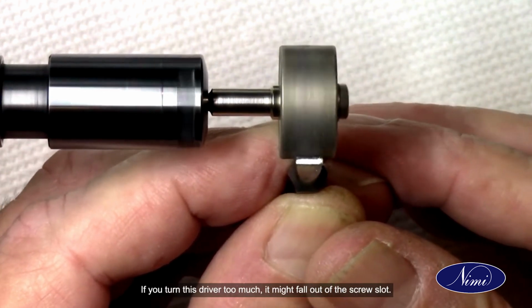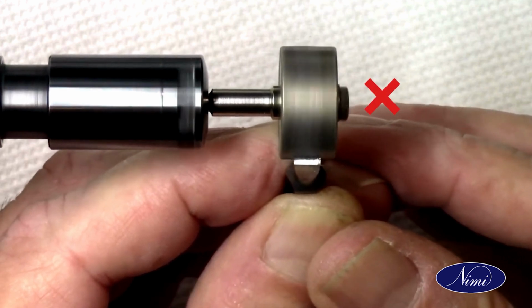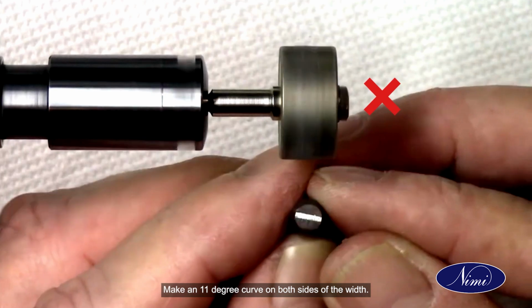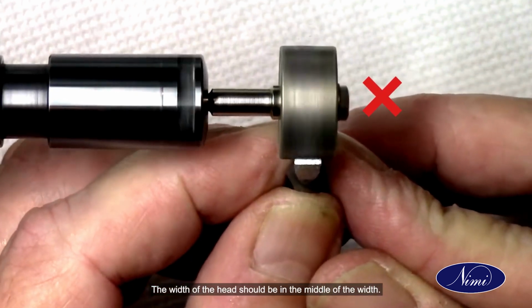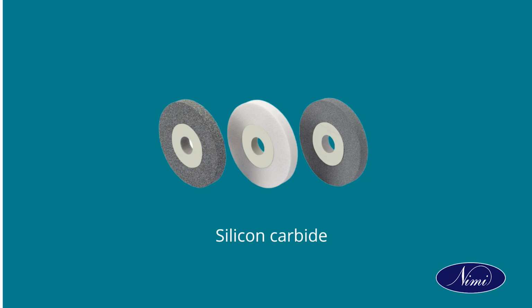If you turn the driver too much, it might fall out of the screw slot. Make an 11-degree curve on both sides of the width. The width of the head should be in the middle of the width. Never use a silicon carbide grinding wheel to grind a screwdriver.